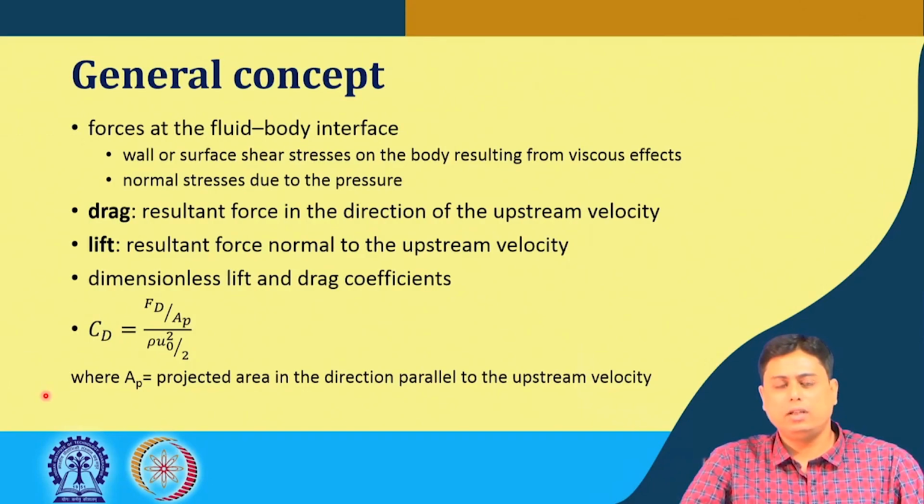If the surface is angled at theta with the horizontal or conventional x plane, then the cos theta component contributes to the drag force, the shear stresses, and the vertical or normal component contributes to the lift force.